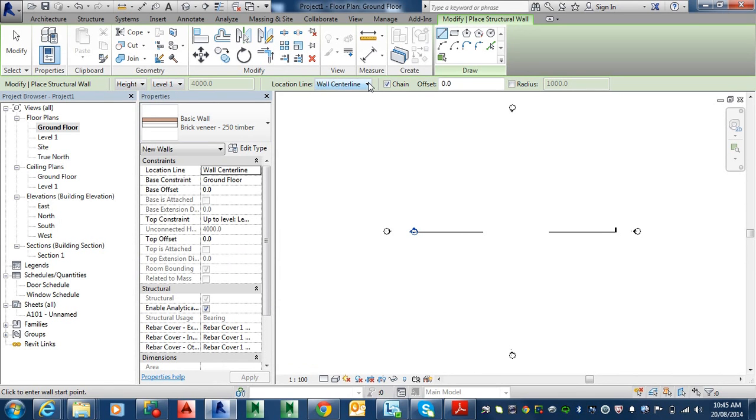Am I drawing wall centers? Remember when we were doing the polysolid, we changed the settings so it's center, left, right, whatever. Here we've got options of whether we're drawing to the core center line or the wall center line, which is usually the same thing, depending. I want to go to finish exterior, which is a bit like the left hand option that we used in polysolids.